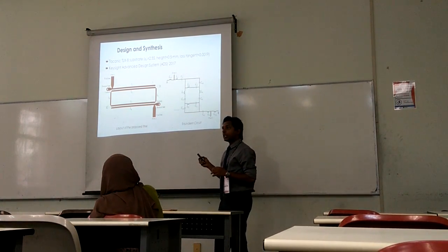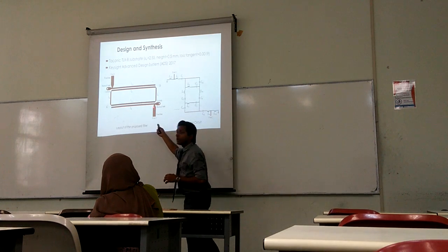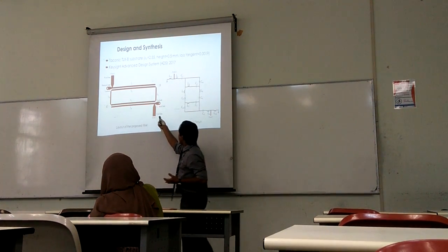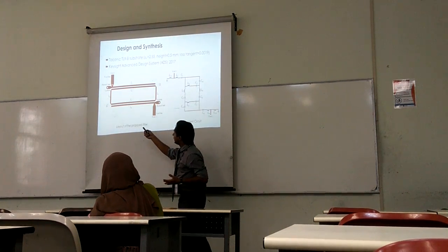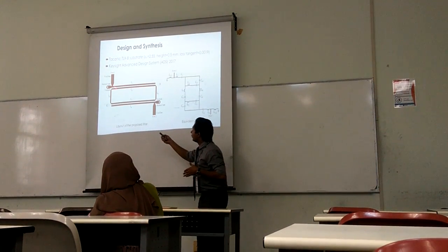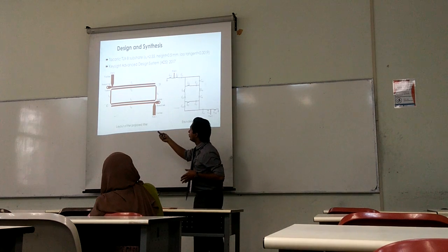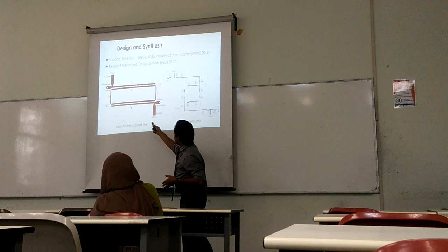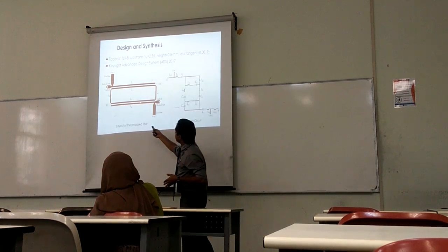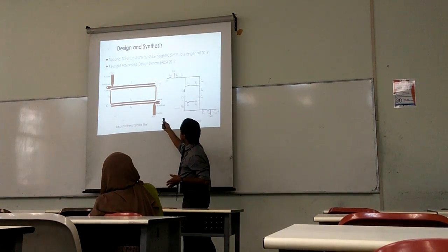And we have used a kind of technique that is called stepped impedance. The width of this feed line, then horizontally the width becomes narrow, and we have used a tapered line to match with this line. And for your information, there's a gap. You see this gap and this gap. These gaps are equal to each other.